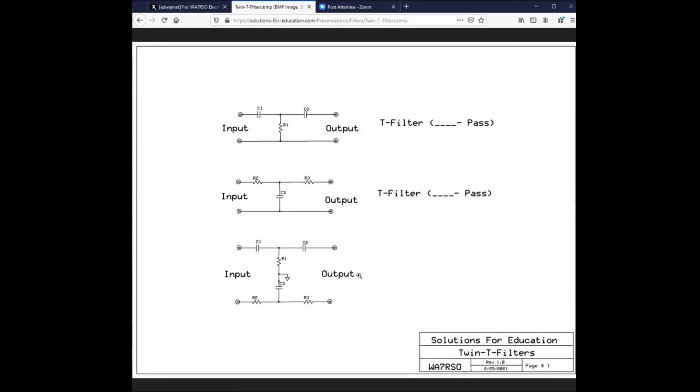And this bandpass filter was made famously by, in fact, Walt, correct me if I'm wrong on this, but I think this was the one that was the Hewlett-Packard tone generator. They basically used this kind of a thing here. Yes, the early Hewlett-Packard oscillator that started the Hewlett-Packard company was a twin T oscillator circuit. Wow. It was real stable because they came up with the idea of using an incandescent bulb as the stabilizing factor. Now, let's go on a little bit further.